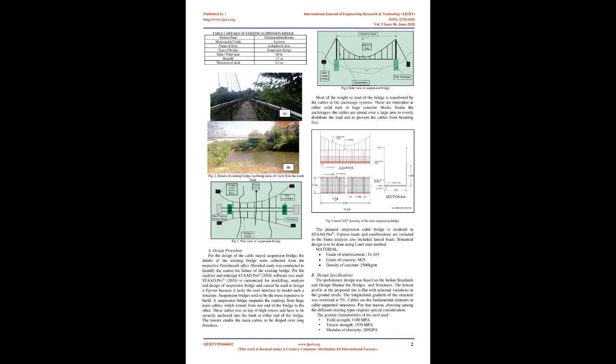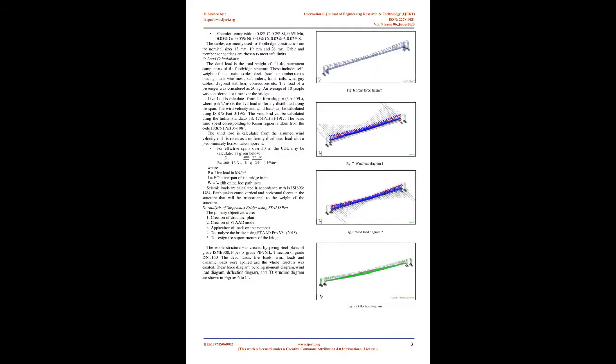A. Design procedure. For the design of the cable-stayed suspension bridge, the details of the existing bridge were collected from the respective panchayat office. Detailed study was conducted to identify the reason for failure of the existing bridge. For the analysis and redesign, STAAD.Pro 2018 software was used. STAAD.Pro 2018 is customized for modeling, analysis and design of suspension bridge and cannot be used to design a flyover because it lacks the user interface to model such a structure.